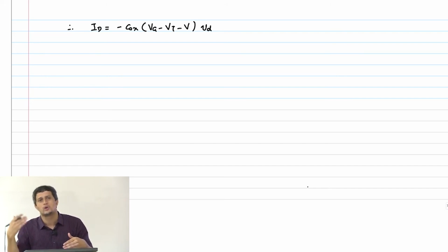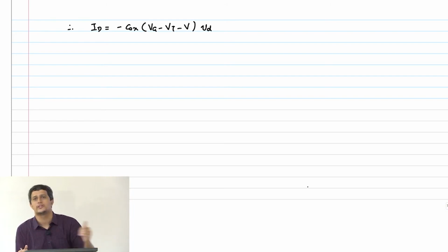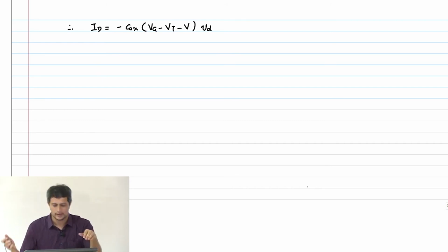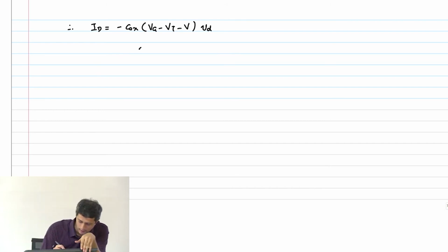There's a continuous generation recombination process that happens. So it's not that the electron can just accelerate as if it's a free path, and therefore it gets related to the electric field through the term called mobility. So if you look at the drift velocity, this will be mobility of electrons into the electric field E.